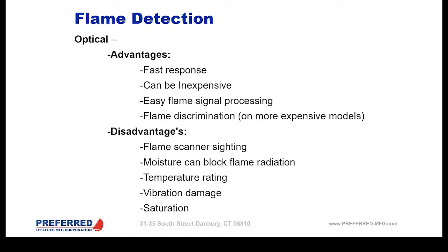Correct. I've seen that. We refer to that as saturation, and it can be hard to diagnose because it's happened to me a couple of times when I'm firing oil and I have a great oil flame and I have a great flame signal, and then I trip on flame failure. My flame signal was 100 out of 100 just right before, and it's because the scanner saw so much IR radiation that it lost that flicker that it's looking for and shut down. It showed no flame. Right, right.